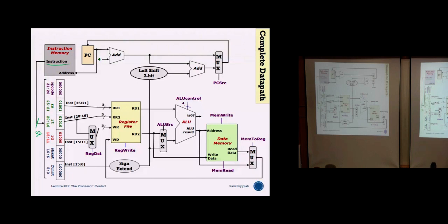Okay, so we saw that this position here, in almost all cases, refers to your RS, correct? So that will, by default, give you one of the operands for your ALU. And we saw that the second operand for the ALU could come from your register or from the immediate value.